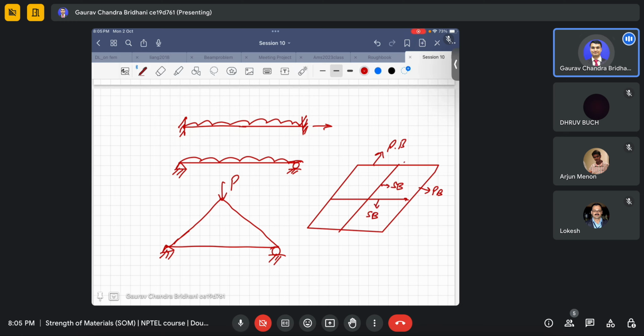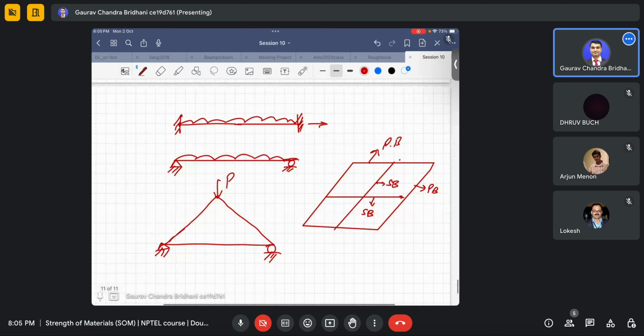Okay, so if I put a primary beam here, and if I make my secondary beam simply supported, will there be a movement at this point? There won't be movement, no. So this edge and this edge won't move, but they will rotate. That means it will rotate, and that same rotation will be passed on to the second primary beam.